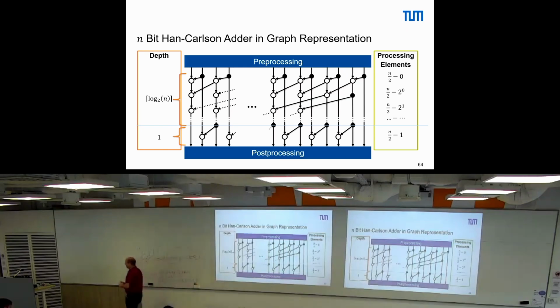So maybe we draw the two basic things: the carry save adder and the ripple carry adder. How to draw a ripple carry adder for, let's say, 4-bit addition. So for 4-bit long input words. We want to base this not on logic gates, just on building blocks. So we have 2 inputs, another 2 inputs, another 2 inputs, another 2 inputs.